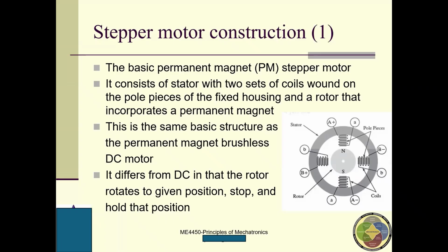do something. For example, in my laser cleaning lab, in the machining lab, we have 2 step motors, one controls the X direction, and another one controls the Y direction. So if we want to machine this part, we can just specify how many steps you want to move in the X direction and the Y direction, and then you just stop. After you finish the machining at this point, you can go to the next desired location. Okay, that's the beauty of step motor.